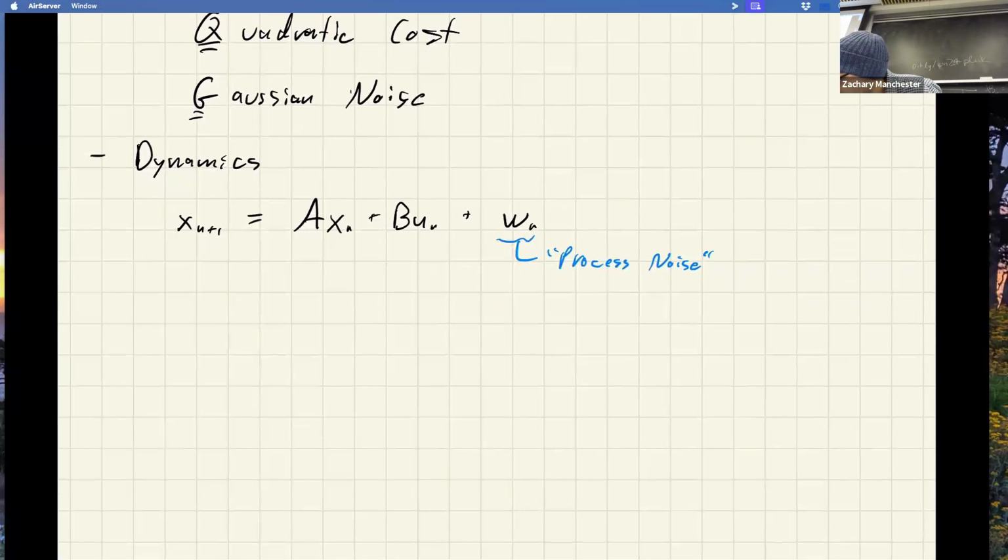And then on top of that, we talked about this whole measurement model thing and how now we don't get to see the state. We just get these partial observations. And those are going to look like this, y equals C of x. So that's a linear measurement model, which is fairly useful actually, right? So that would be like, I just get the pose and not the velocities. The mocap example actually fits this reasonably well. And this we're going to assume also has noise on it. So this is going to have this v_k added on, which is called measurement noise. And so this is your sensor noise. So here we've got these two different kinds of noise. One is driving the dynamics, so the dynamics are actually stochastic. And the second one is modeling your sensor errors, your sensor noise.